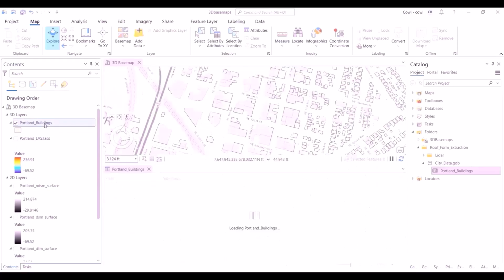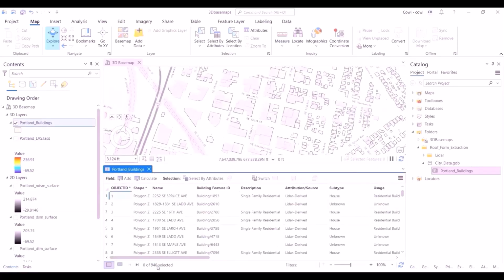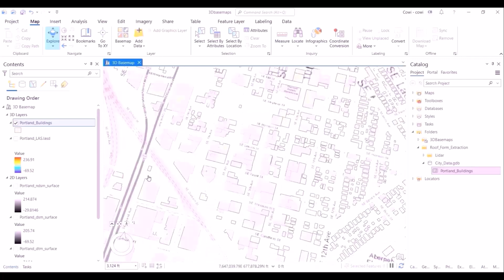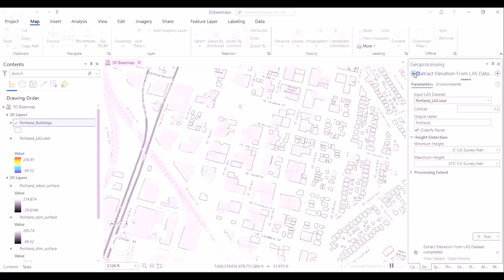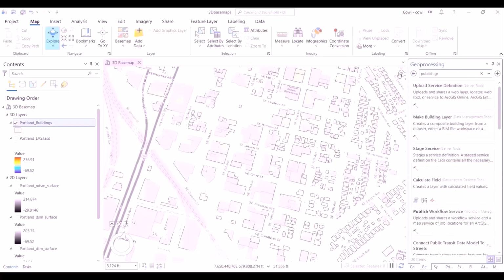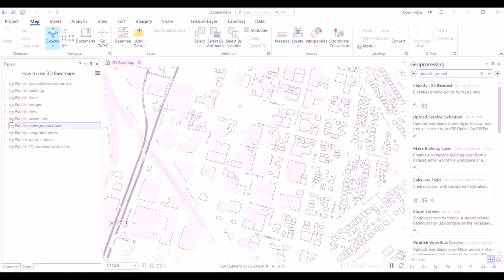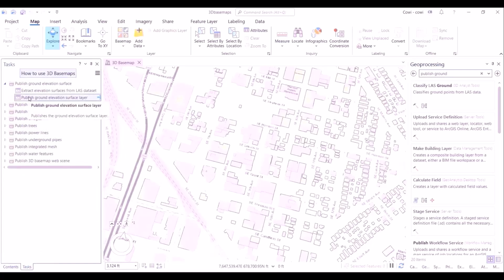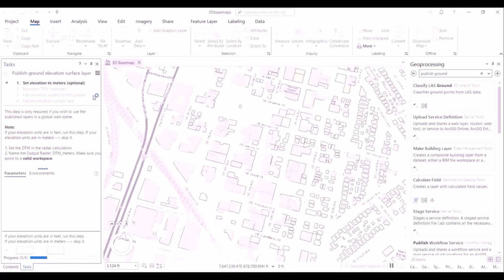Subsequently, you would have noticed that the values of elevation are mentioned in feet. This is to demonstrate that using a raster calculator, we can convert these values into any particular dimension which we choose to capture. In this case, we will convert it into meters, units of measurement.